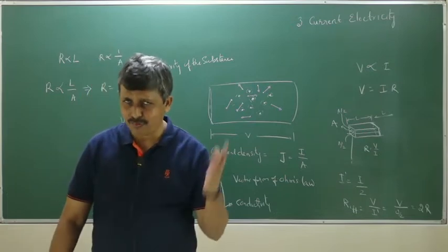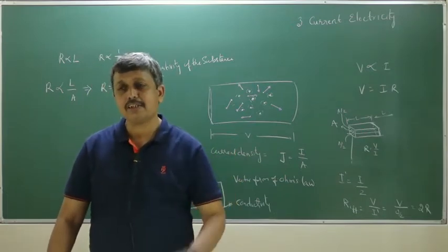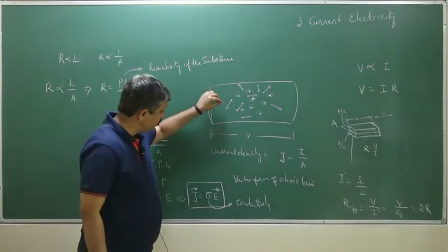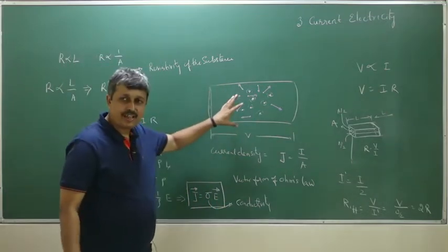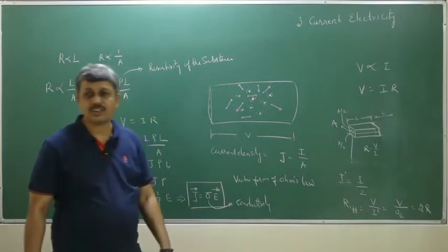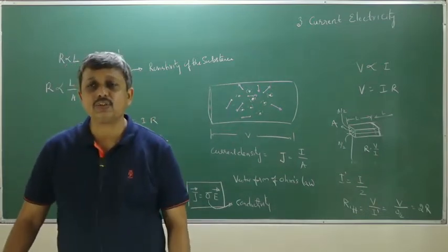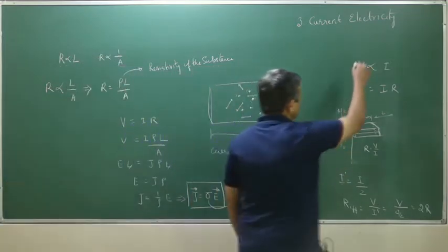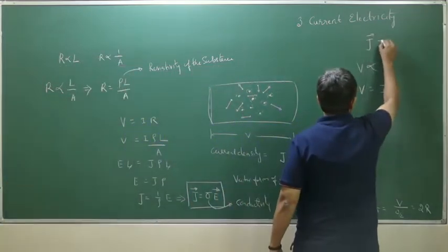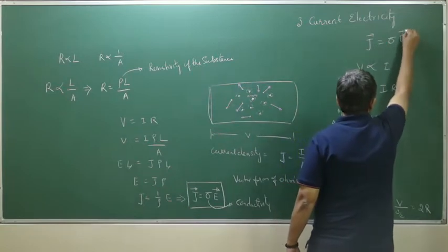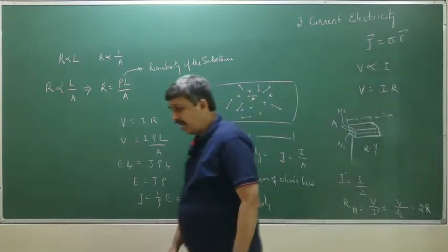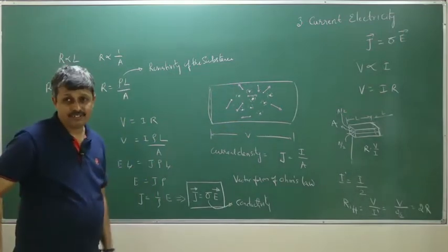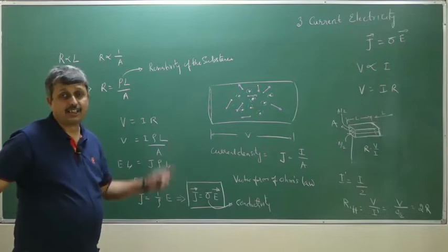It is not different from the Ohm's law in electricity that we studied, but it is giving us values at that position, instantaneous values, in a vector notation. So J is equal to sigma E. Now we are going to take J is equal to sigma E as our Ohm's law, and go ahead and see whether this sigma has any relation to the micro parameters inside the conductor.